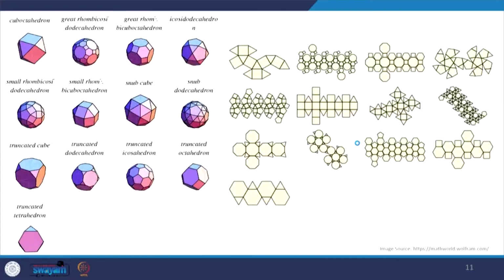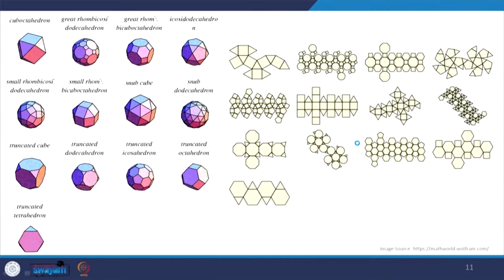Now we will come to surface development for Archimedean solids. If you remember, there are 13 Archimedean solids that we know of, and these solids again follow some order. It is not just one single shape. In Platonic solids, we just have one single shape which is repeated, and it follows a rule that at each point there will be 3 surfaces meeting, or 4, or 5. That's what gives us these 5 Platonic solids.